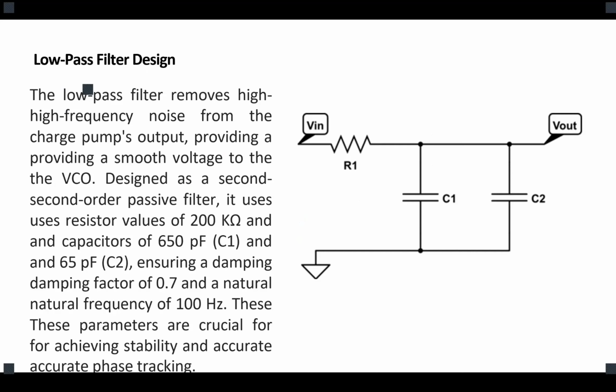The filter is pretty simple. We already talked about the low pass filter. For example, here you can see an example of an RC filter that works with a PLL. The values are actually perfectly designed for a 60 hertz system. So with these values, you could filter out all the other unwanted noise, and you have a stable, pure signal at your voltage controlled oscillator. Very good.